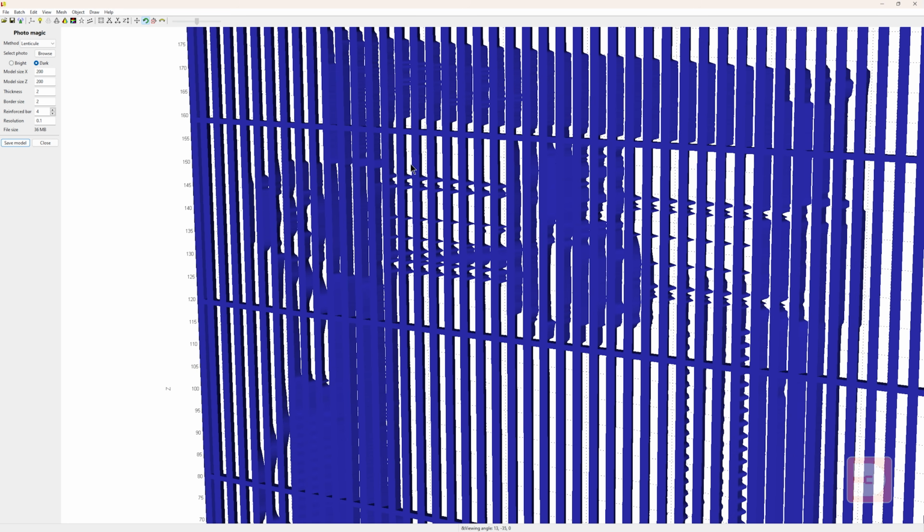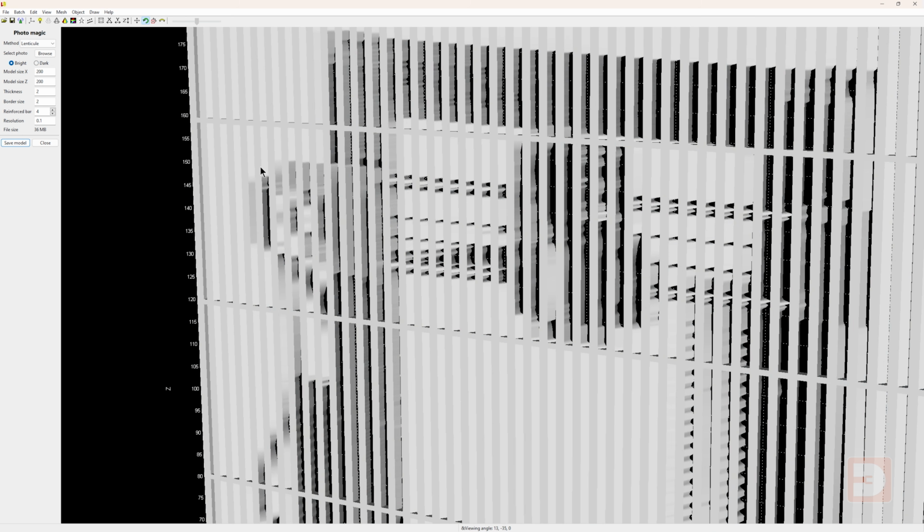Dark mode leaves gaps where there is a lighter part of the model and tries to fill in the darker areas with the model. The other thing that's important to note here is that bright mode allows there to be shadows, which will add significant detail under the right lighting conditions, whereas dark mode doesn't allow for shadows, so will present more of a block edge image focusing more on negative space.